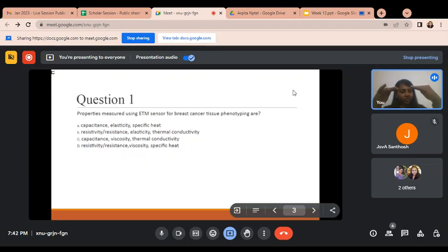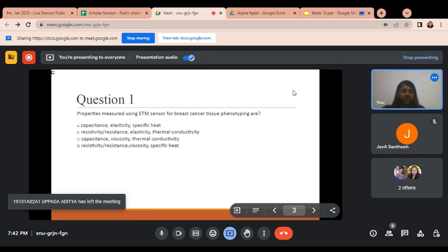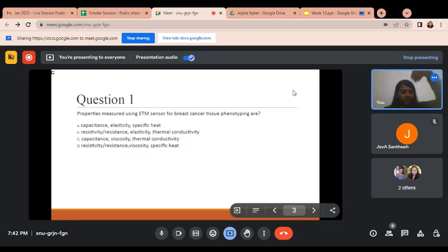whatever happens when we go for the developing process, some portion of the photoresist remains, some portion is gone, according to the nature of the positive or negative photoresist, or whether it is a dark field mask or a bright field mask. So when we dip the wafer into the etchant solution where the photoresist is not present, in that portion the etchant will start to work, and it will etch the underlying deposited layer.